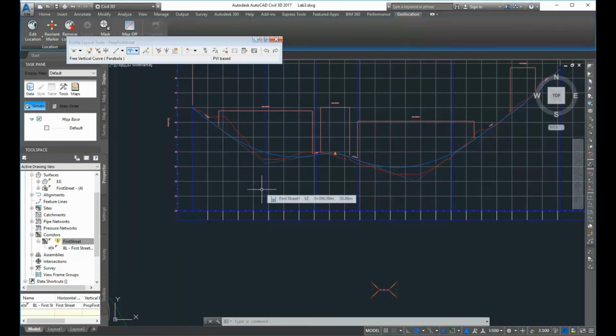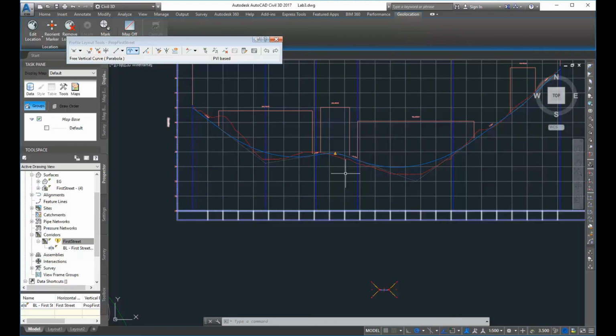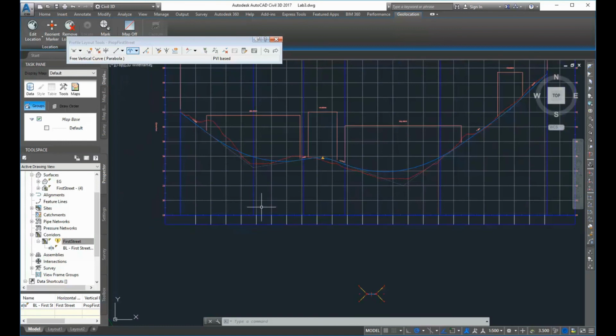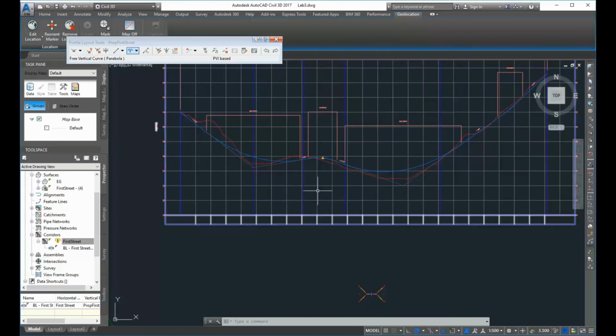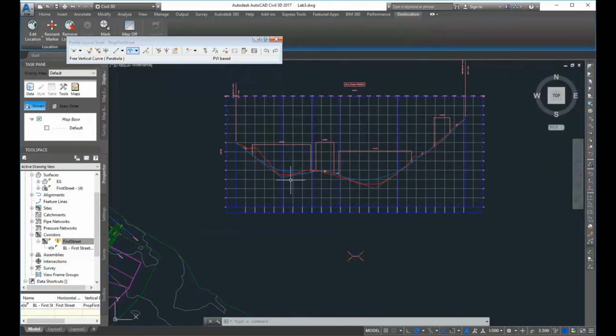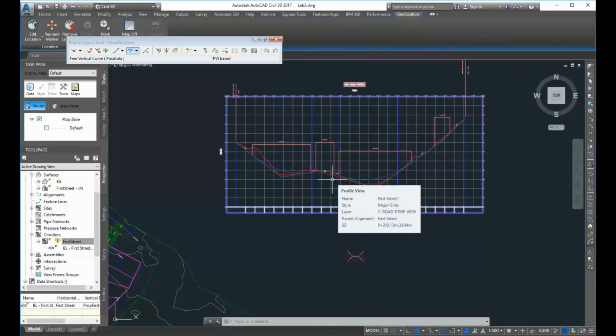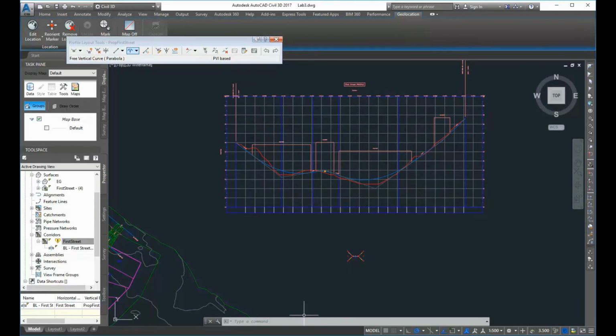Okay, so for your assignment, you're going to be doing something similar. You're going to be generating the earthwork for both of your alignments, and we're going to start putting some cost to them, which I'll talk about in a little bit. But just a little bit to wrap up the changing of the earthwork. The primary things: you make changes to the blue line, your vertical alignment. You make sure you're always rebuilding your corridor, and then you're running your earthwork. For your project, you only need to keep in your spreadsheet your very initial earthwork and your final.